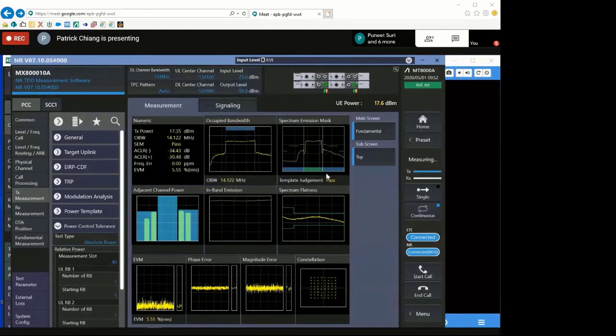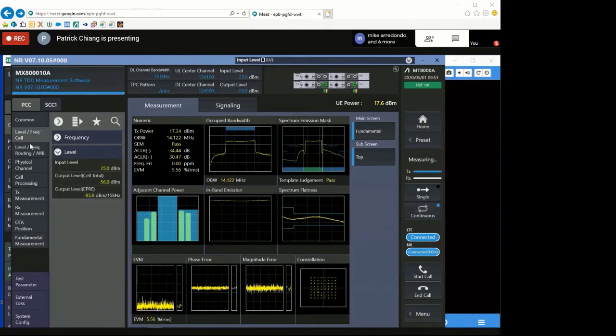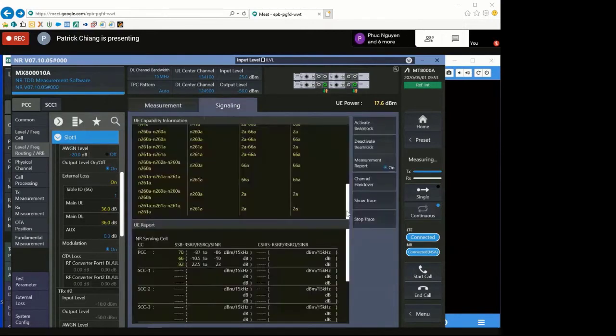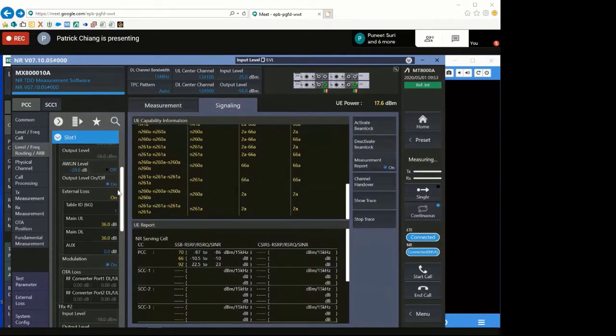Do you know why the UE is not going up to 23 dBm? Okay, maybe because my path loss is only set up for downlink, right? This is an FDD channel. Currently I set the path loss the same for downlink and uplink. Remember I turned on the measurement report here. That's how I estimate my path loss, because I don't know it, since this is just OTA. I estimate it by seeing how much power the UE says it received.